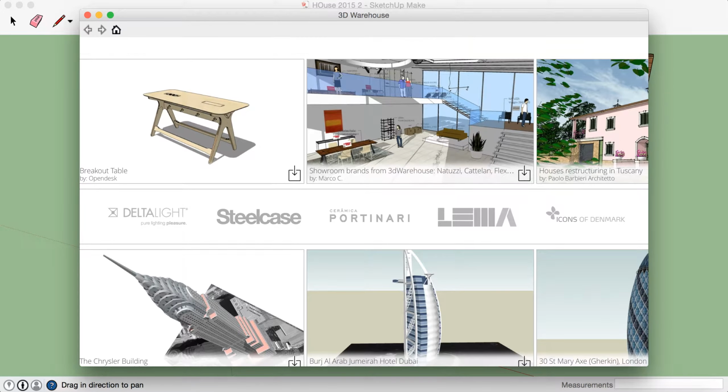If I want to move this window up to the correct place, what I need to do is get the orbit tool, so I'm facing my window, like a straight on view, and I can use the Move tool to move it up and down. So I'm going to move it up to about the right place. But if I then orbit around, we can see it's sort of floating off the side of the house there. So what you've got to do is then a similar thing, but this time we'll do a bird's eye view, so we're above the house and the window.